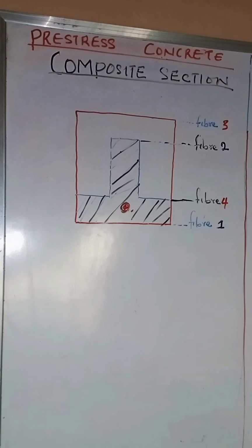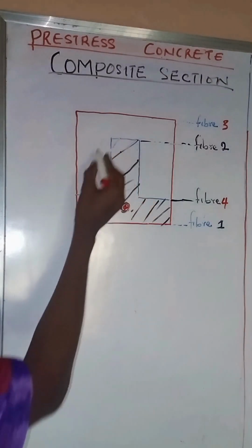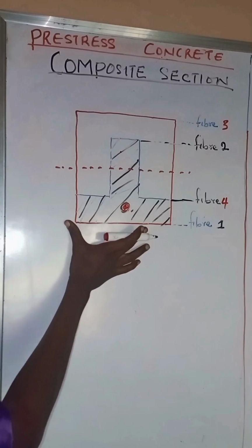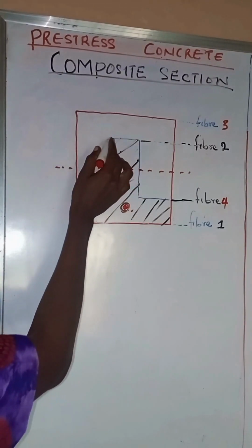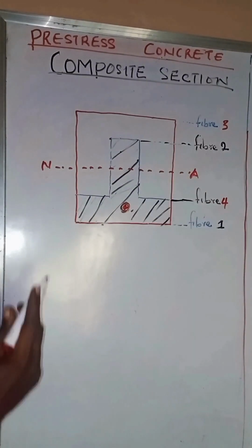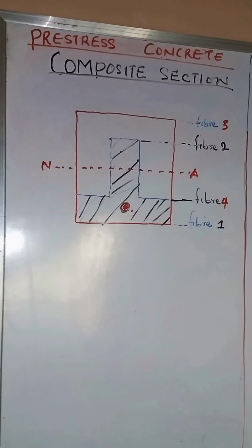So if the precast beam is not propped and we have the beam neutral axis lying within the precast section, we are going to have the composite beam. In other words, if your neutral axis lies within this shaded region, anywhere from here down to here, that is a case. All right. So we can have the system not propped and the neutral axis lying within this precast section.